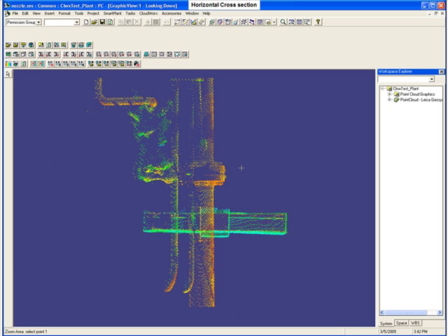Okay, so the flange workpoint tool. With a point cloud isolated, either by clipping planes or by limit boxes or some other process, you can start to get the flange workpoint. The flange workpoint is the center in between two flanges and where the gasket is.